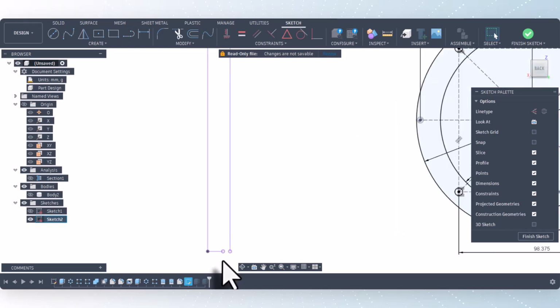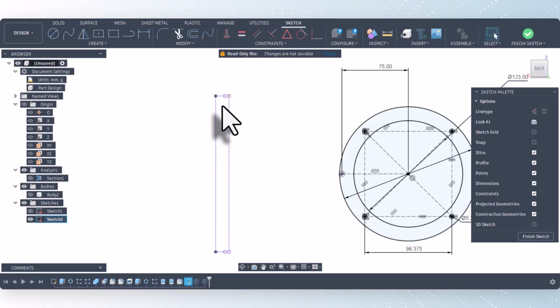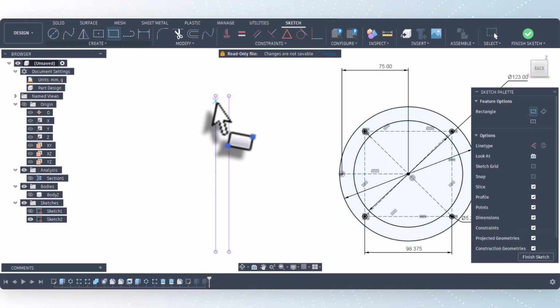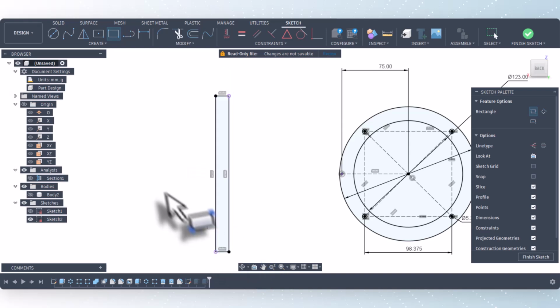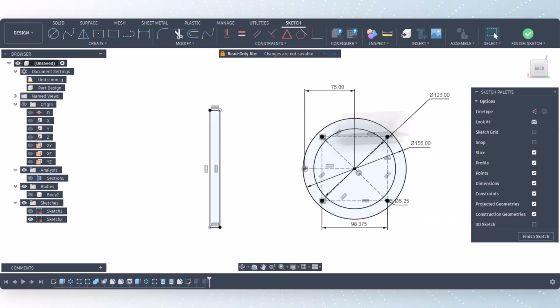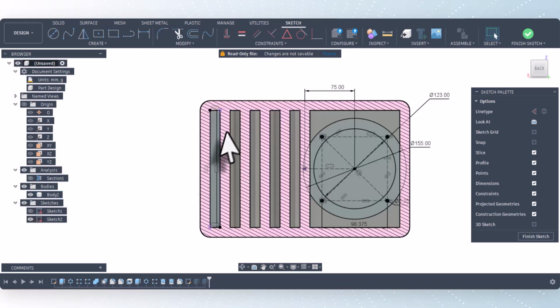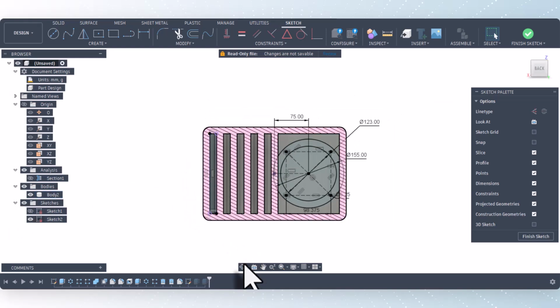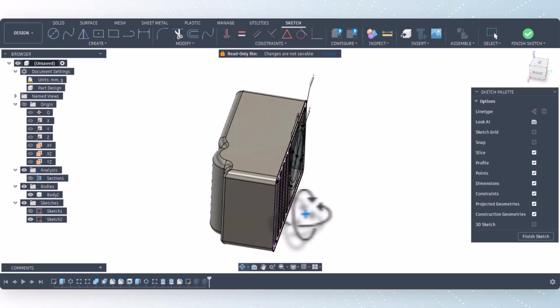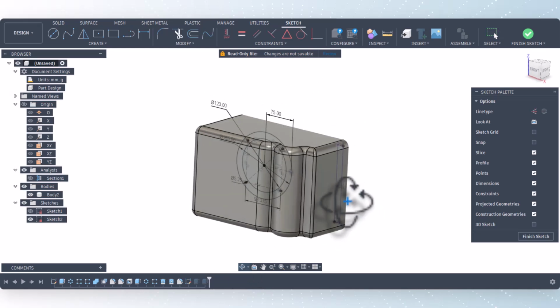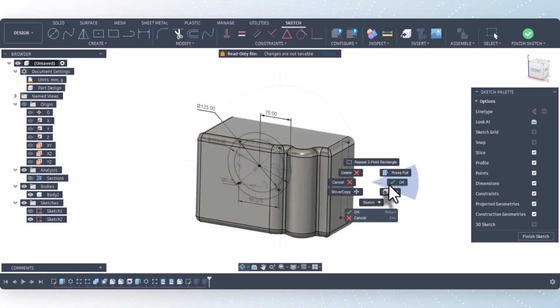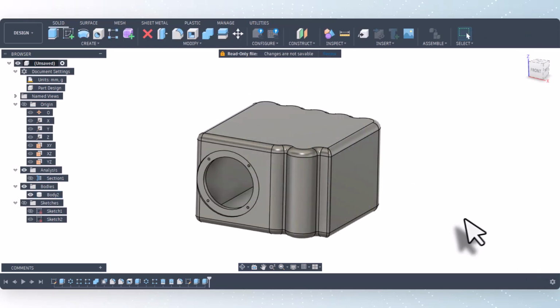And I'll put another rectangle because there's an opening down here and an opening up here. I might just delete these 2 lines as well. And then I'm going to put a rectangle across here. So I'll put it from here to here. Now notice I don't need any dimensions if I do it this way, because it will always adapt to the size of the body, and then if I change my dimensions, that is going to update automatically. All right, let's go back and finish sketch, and let's make that sketch visible.